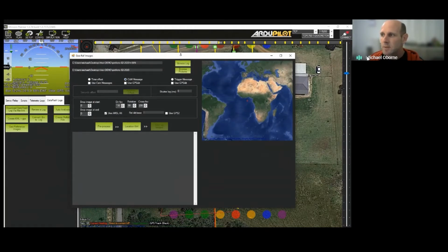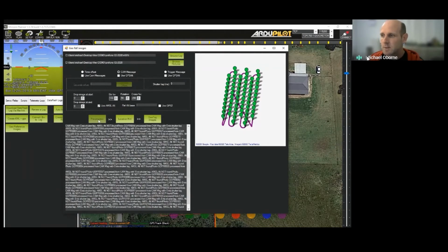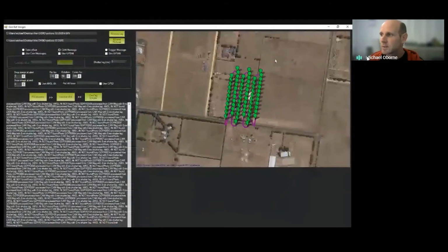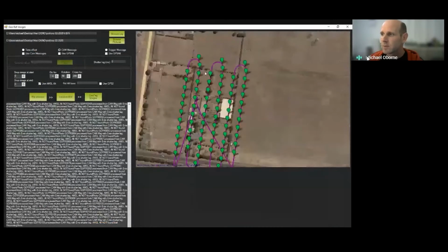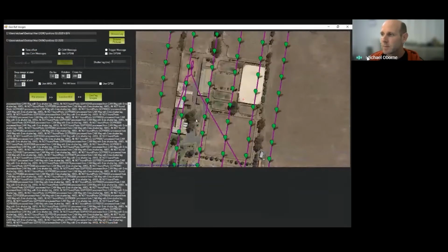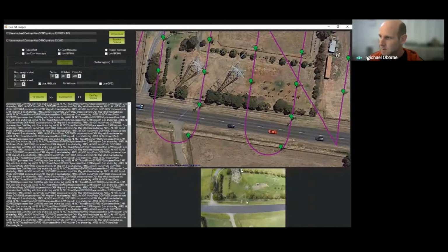And so what this screen does is it reads the log and will try and read all the information from the photos to try and correlate them and to try and tag those photos. So I'm going to click pre-process here. And what that's going to do, it's going to process all the logs and show us where each photo is. So the path the drone took and the photos on the map. So say this one here. This one here looks like it was close to the road. So I'm going to click it. And sure enough, looks like it's pretty accurate to me.